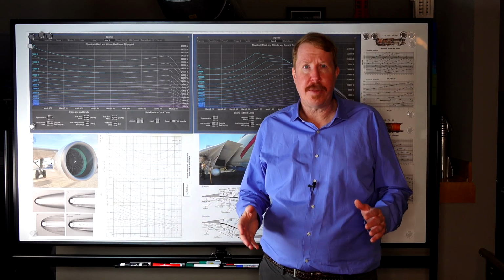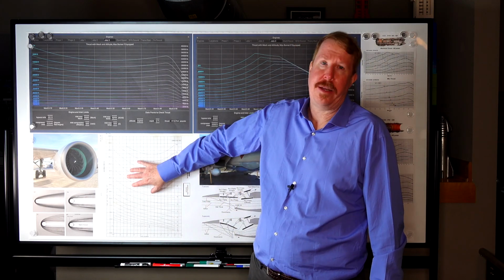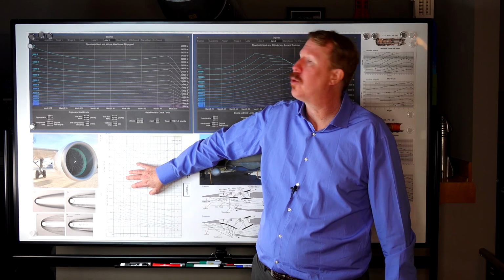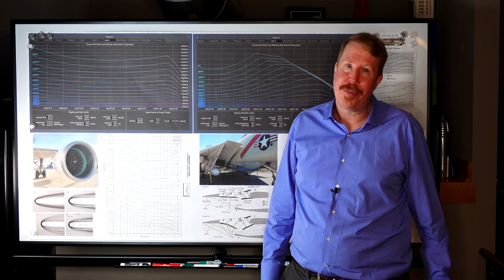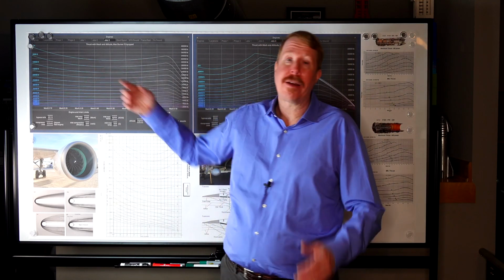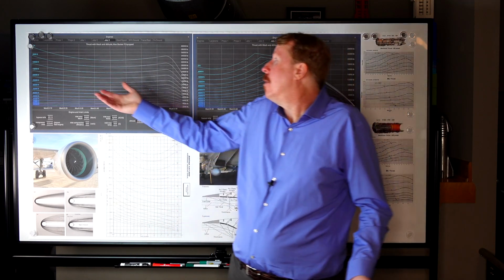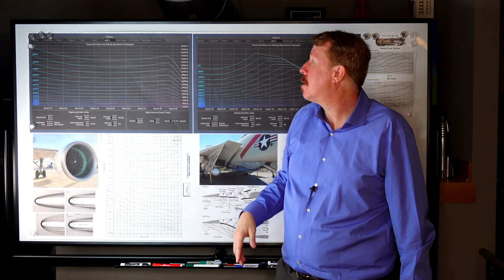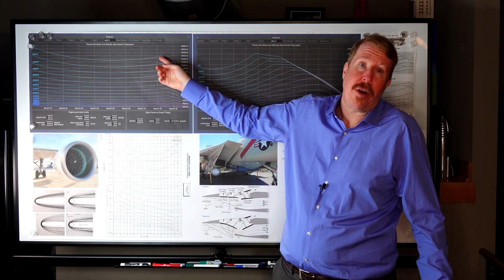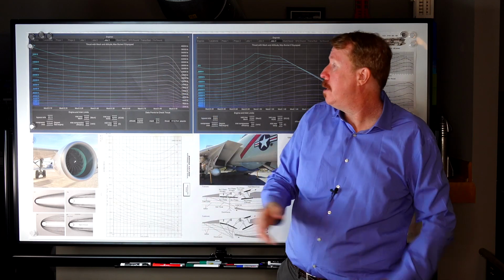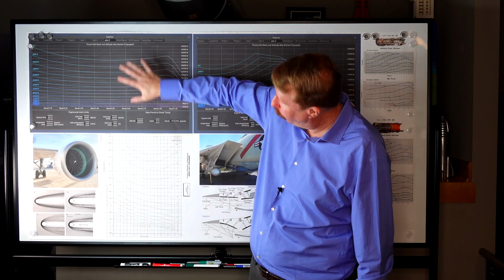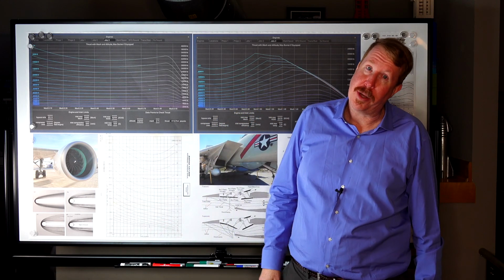And what I love so much about this data is it's directly derived from the actual jet engine. These curves are derived based on very simple math. The math is simply taking a constant power and running the thrust down as the speed builds and using Bernoulli's law to apply ram air effect to then turbocharge that inlet as it speeds up. The very simple first principles math matches these thrust curves so well.